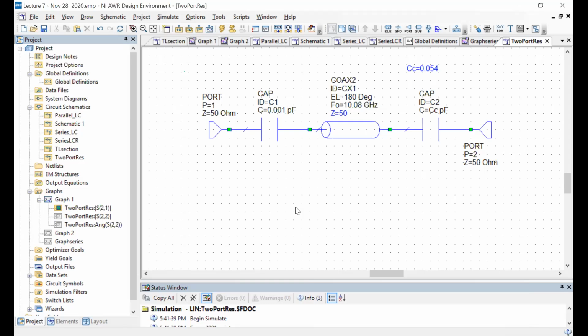And the power leaking out of that port is also so small compared to the power which will leak out of port 2 in reflection that the additional loss from this is insignificant. Yes, and which is why we were seeing the modulus of the reflection coefficient stuck at 1. From port 2, yes, exactly. Okay, anything else?